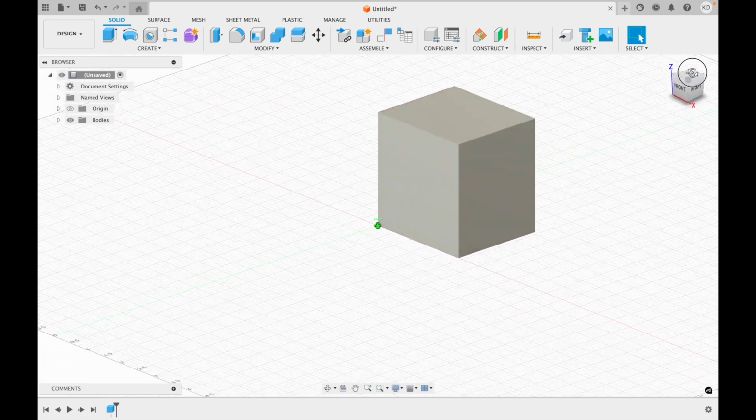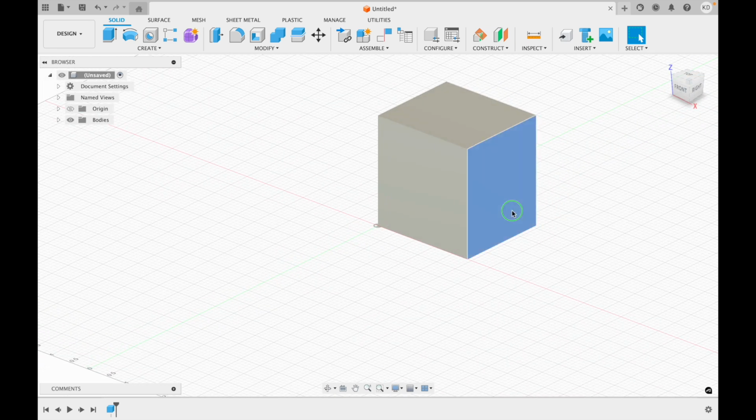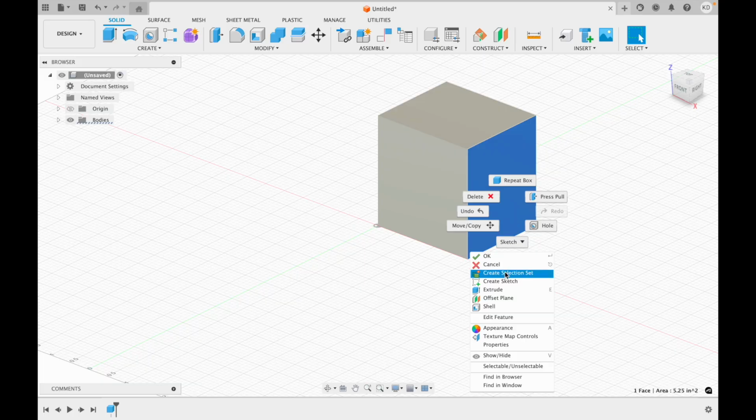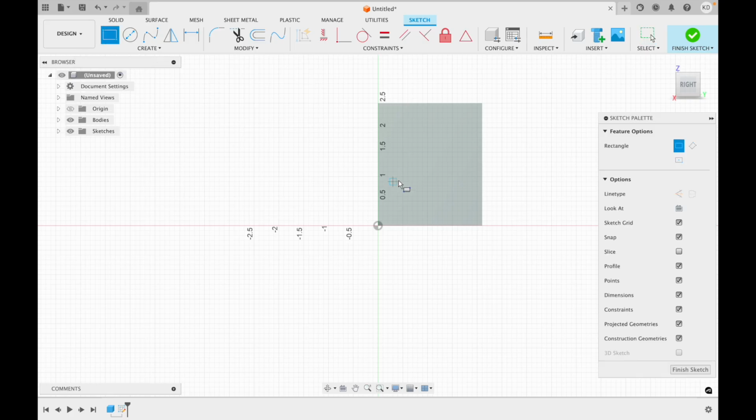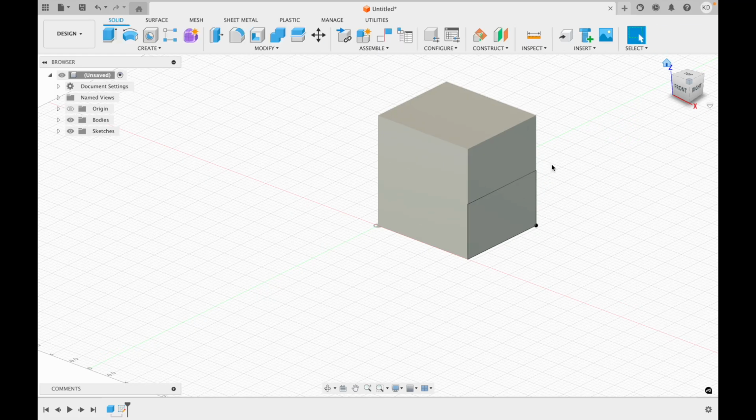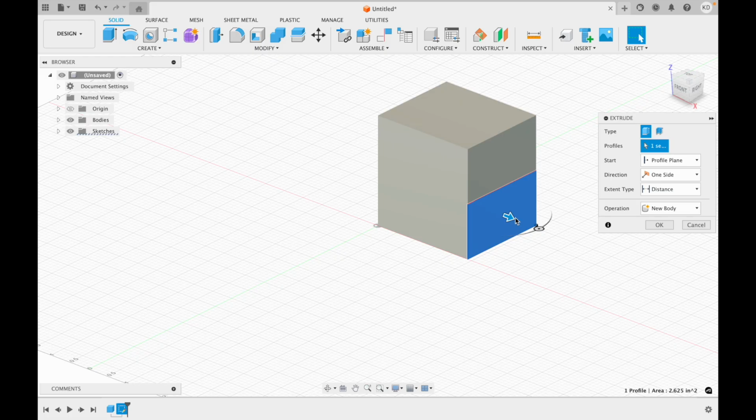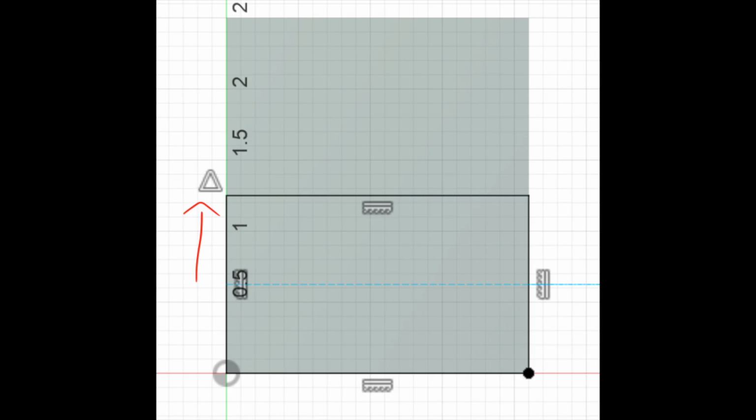Another unique function in Fusion is that you can create a sketch on a plane, which we've already talked about, but you can also add it to an existing solid. You essentially create a sketch like I'm doing in the video, drag it out, and make that a specific thing. With that, you can just extrude it and make an even more complicated shape. I want to take a quick sidestep. When adding shapes or sketches to existing geometries, that triangle just means that you're in the center.